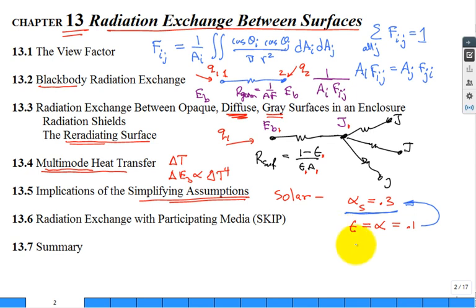A lot of times they'll even put the solar absorptivity divided by the hemispherical emissivity or the hemispherical absorptivity. And if this is a large number, and I showed a table where they put that in the textbook, then especially if you lay something in the sun, it can get very hot compared to another surface with that being closer to 1, and you lay that in the sun and it won't get as hot, high temperature.